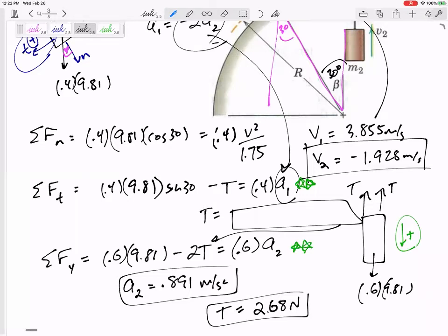I haven't made the test, but I'd go back through all the problems we've done and look at the process. Free body diagram, sum of the forces, and define your axes, normal, tangential. Sum of the forces in normal equals MA normal. Sum of the forces tangential equals MA tangential. Sometimes tangential is into and out of the page, and so we didn't even sum the forces tangential. We sum the forces in Z equals MAZ, which might be 0 for some of these.